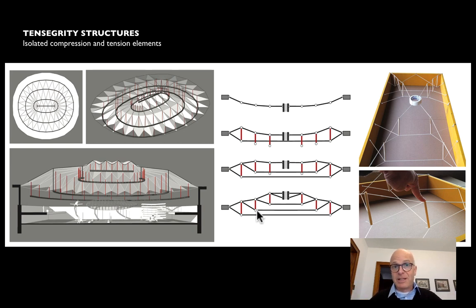It's a very flexible structure, but you can see also that it has these two load paths, right? It has cables that are coming down that are supporting the weight of the truss, but it has cables going in the other direction up, and you can sense a kind of positive curvature here to those cables that holds the roof down in the event of a big wind.